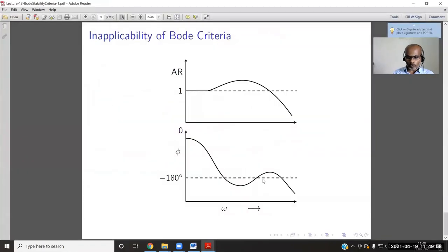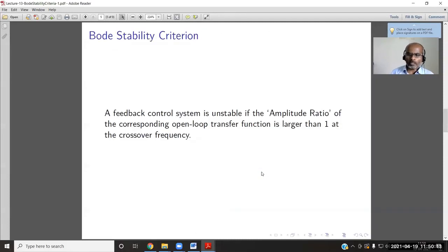You know what is an open loop? Normally there is a closed loop. You will cut the loop after the measurement, so the measurement is not given to the comparator. So you have all the elements in the loop now. For that open loop, you make the Bode plot.